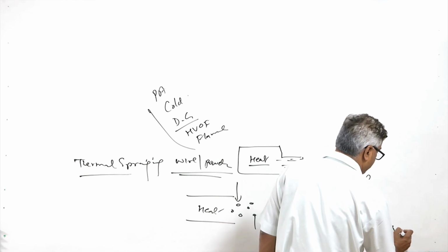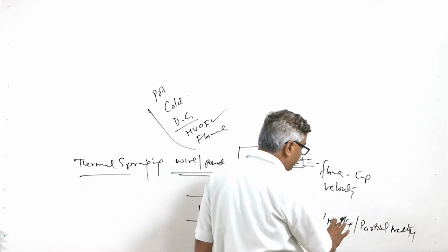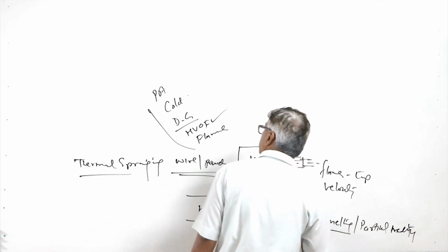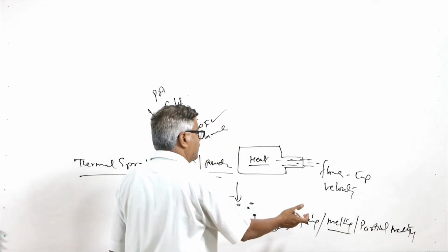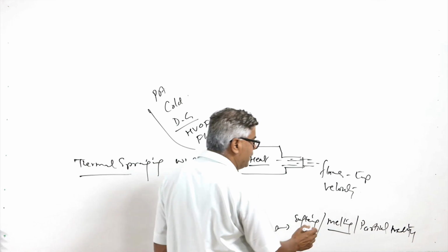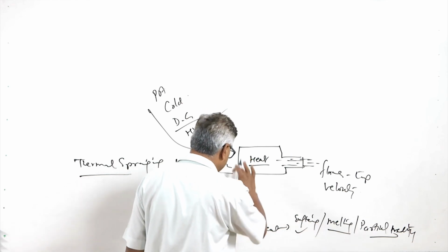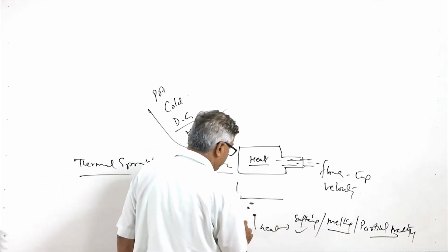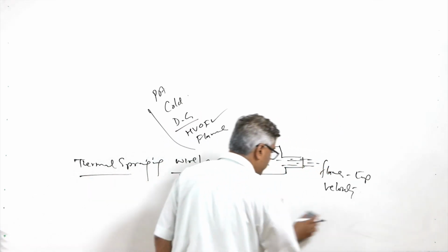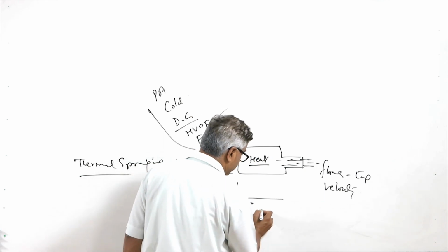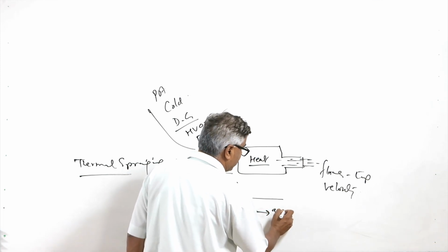For example, in the high velocity oxy-fuel process, the HVOF process, there is just softening, no melting, but melting takes place in the flame spray process, like the low velocity flame spray process. So in detonation gun and high velocity oxy-fuel processes, mainly either partial melting or just softening takes place. These particles, when they are added into the heat source, will be moving with the heat source. Depending upon the kind of heat source or suitable process being used, these particles will be heated, melted or partially melted, and then they will be accelerated.